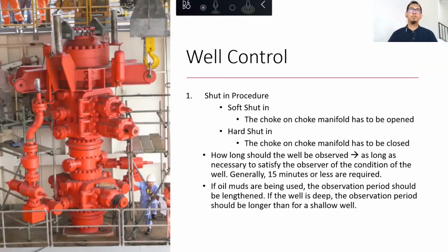And once you do the shut-in, you need to do the observation. So how long does it need to be observed? As long as you need. Sometimes it takes 2 hours. Sometimes it only takes 15 minutes. It depends on the condition of the well. If it's an oil-based mud, normally it takes longer than that. If it's a water-based mud, normally it's shorter than that.